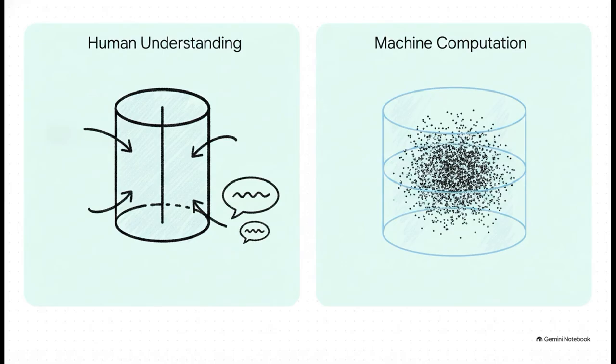Okay, let's dive into this. Take a plain language definition of cylindricity. All points of the surface are equidistant from a common axis, right? We all understand that conceptually. But conceptually just isn't enough for a machine. A CMM requires a minimum zone solution. It has to mathematically constrain a massive set of points between exact calculated boundaries. It's the exact same rule, but only one of these definitions can actually be coded into an algorithm.